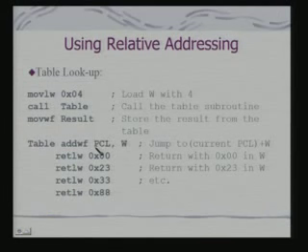If you see here, the current content of W will be added to PCL, and you will be jumped to the current PCL plus W. So, the moment this offset is added, the current location is this PCL plus W, and this has been done through an arithmetic operation. We have not executed any branch instruction at all. This is very, very interesting. We have not executed any goto or conditional branch, we have just done an addition operation.